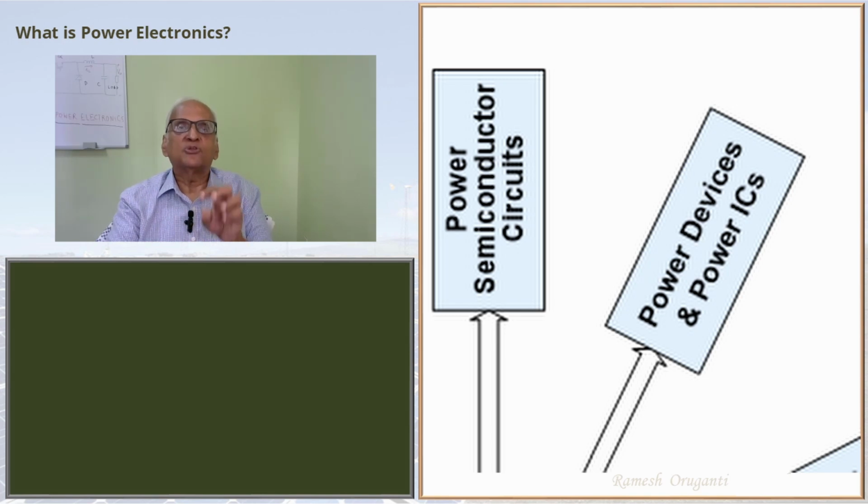These devices are used in the power converter circuits. So a power electronic engineer definitely has to know about them also. You might notice that I have mentioned power ICs also. These are power integrated circuits. At the low power end, the power semiconductor device and a large part of the auxiliary circuits can be put together to form a single IC in order to save space.